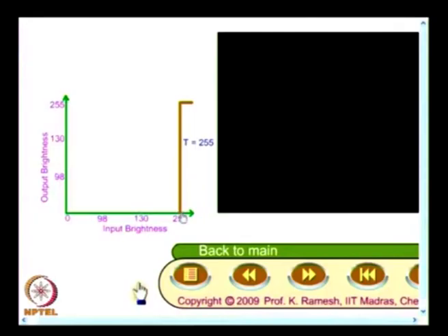Here I have discretized from 0 to 255. Up to 255 I make everything black, and at 255 I make it white. That is why you see this as a black picture, because we have seen that the image has 0 as pitch black and 255 as white. Now, if I make all the pixels black, I will not see the picture at all. But photoelastic images have high contrast, so you are in a position to apply a very simple image processing approach called thresholding to identify fringe areas.